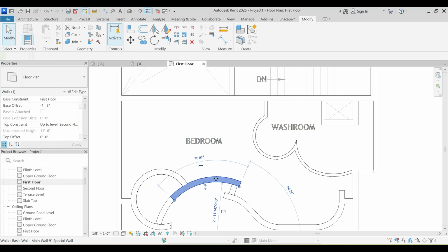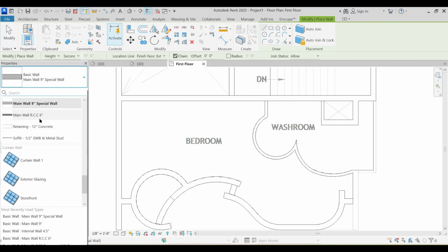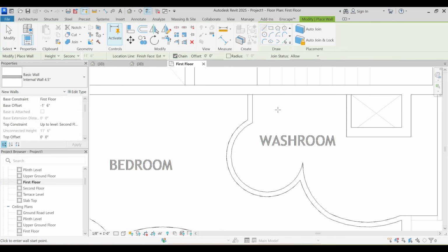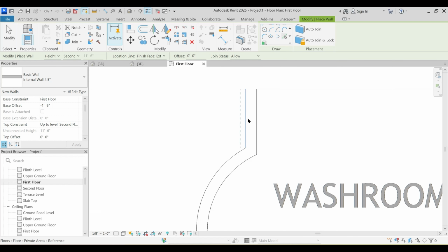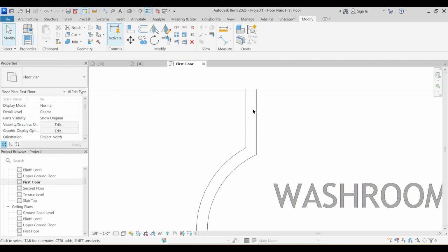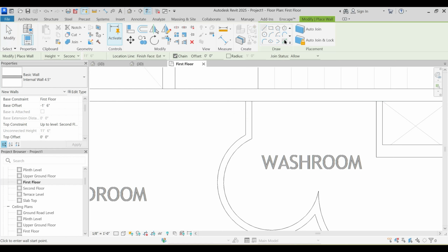Let's construct the same walls. This, no, not the same wall. This would just be a simple internal wall. So WA and internal wall 4.5 and just pick, and hover your mouse until it snaps, press Tab, WA and pick.